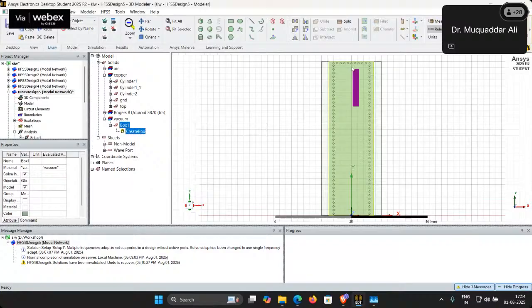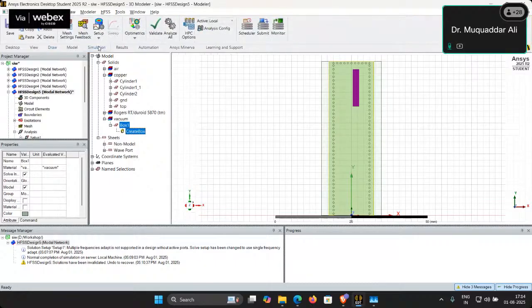we have this slot placed along this side, and this y-axis is the main axis of the waveguide, and this slot is slightly offset to the right side, because if we put the slot in the center, then there will be no radiation. If we make this offset, then we will be having some variations.